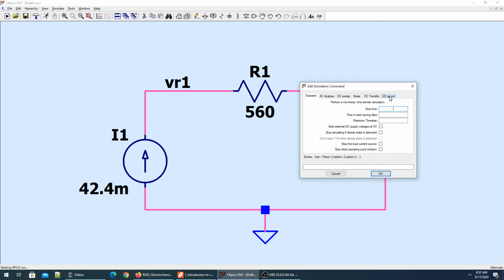Say we have 4 more resistors, 4 more voltage points, 3 more different components with some current ratings. If I do the DC operating point simulation, it is going to analyze my circuit and give me the voltage and current ratings of every element, the voltage and the current passing through each and every element. That's what we're going to get from the DC operating point, and it is going to pop up in the form of a list. But it doesn't give us the power.